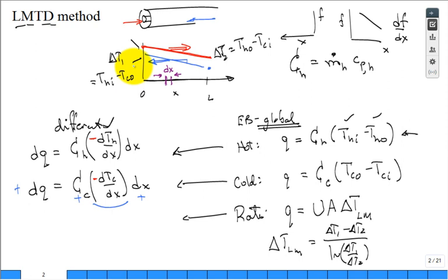Okay. Then we have this equation. What's the analogous equation for the rate? Well, we have dq is equal to overall U times dA times Th minus Tc at that location. Not Thn minus Tcn, no, just at that location. So at that location, I have some little temperature difference that drives that rate of heat transfer. So what is this area? Well, we like to write it in terms of a little dx. So we put a P dx.